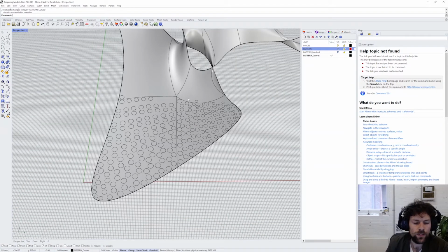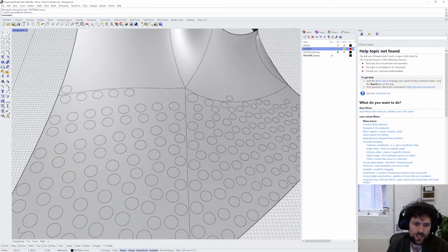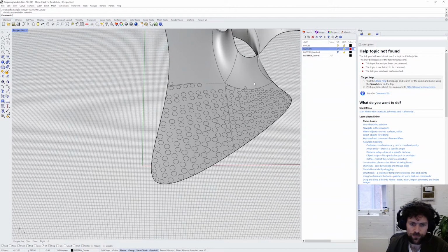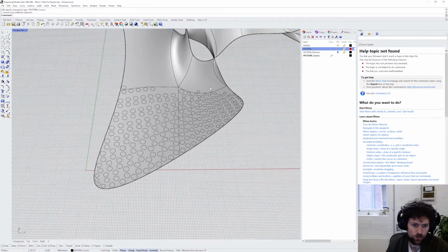These curves in Fologram and in TwinBuild, they're going to be rebuilt as simpler objects just to reduce the detail in the model that's rendered on the HoloLens or on your mobile phone. So you may need to customize the settings to ensure that the number of vertices in these curves that's being streamed to your device is sufficient for performing the task. Usually the defaults are going to be okay.